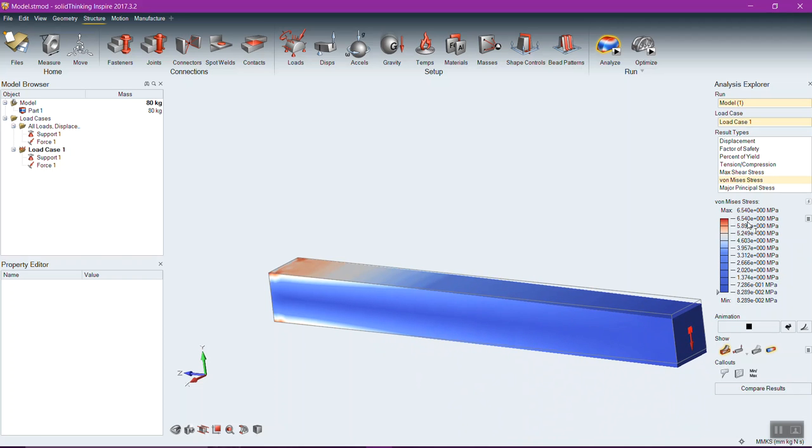So how about the result? Is it more accurate compared to other software? Well, it depends. If you're comparing this to Abaqus or ANSYS, a proven analysis tool, the results should be exactly the same. If you're comparing it to SolidWorks, which is a CAD package first and an analysis tool second, these results are going to be substantially more accurate. But for a proven FE solver, Abaqus, ANSYS, Dyna, Nastran, a properly set up model in any of those codes should be exactly the same.